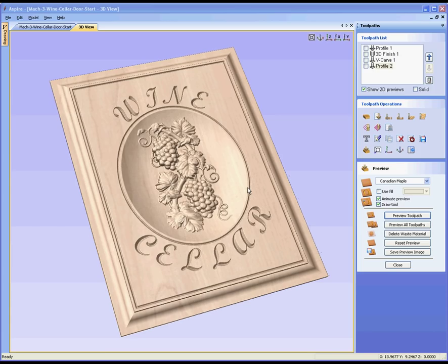And we could have gone ahead and machined that as any regular 3D part using the roughing and the finishing toolpaths. That would have been relatively time consuming, so the only reason for me to do that is if the profile running around the edge is one that I don't have tooling for, or is too complicated for me to buy the tooling to actually cut that. In this case, we decided to opt for some existing tooling we had that could cut a raised panel ogee into the edge of our part, and just use a profile toolpath to do that.